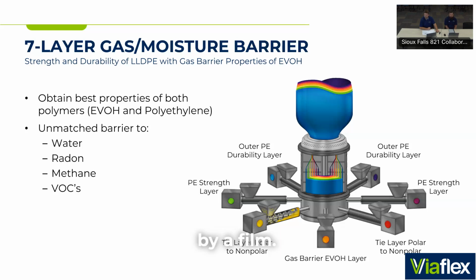They would be separated by a film. In this case, they used 60 mil high density polyethylene films, just straight EVOH films of a couple different mole percent EVOH, and then co-extruded film of polyethylene tie EVOH, like we demonstrated in the previous two slides. They were sealed with Teflon in between the layers and kept at a constant temperature. Samples were pulled from each reservoir at varying intervals to test for the concentration.